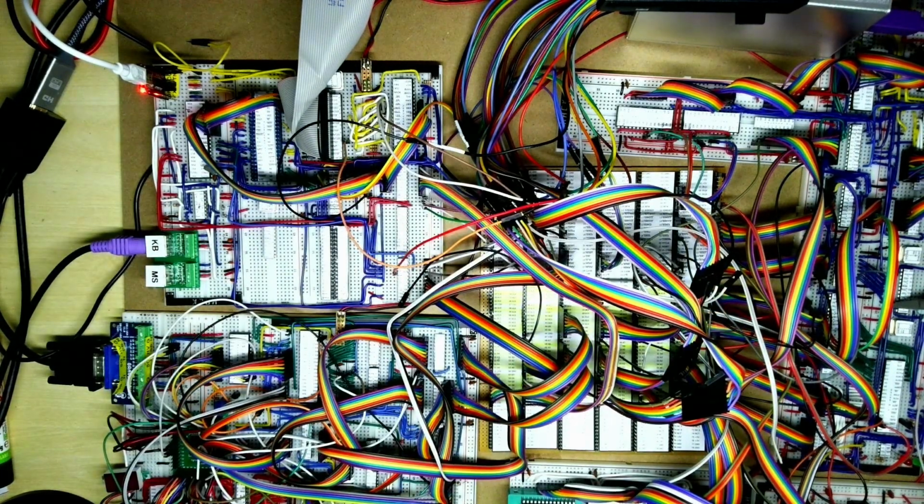Now I've also reconfigured the BIOS so it now supports turbo mode. So this means that one of the registers, the port B registers, one of the bits there can be used to switch between the default 4.77 MHz mode and the turbo mode, which is in fact 25 MHz divided by 3, about 8.3 MHz. So I'm just going to turn that on first of all, and we'll have a look and see whether or not we can configure that first of all.